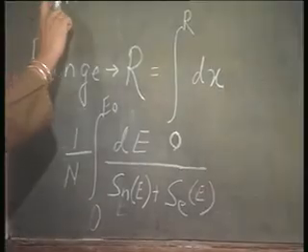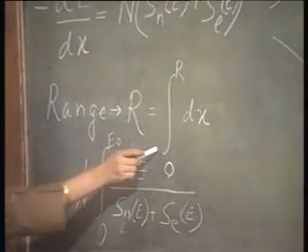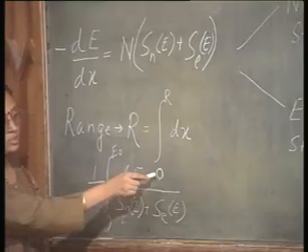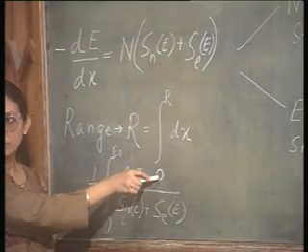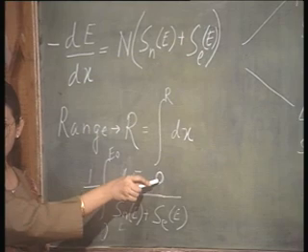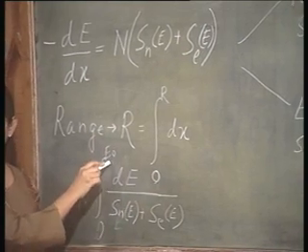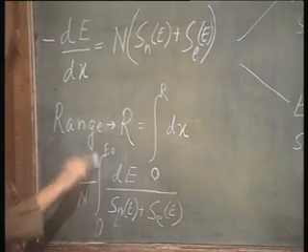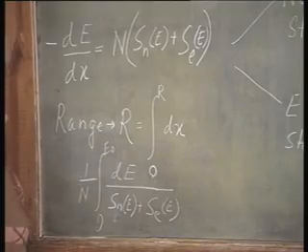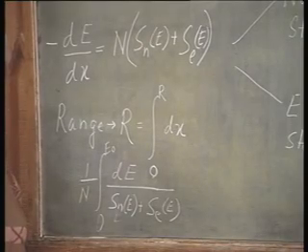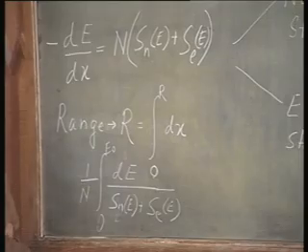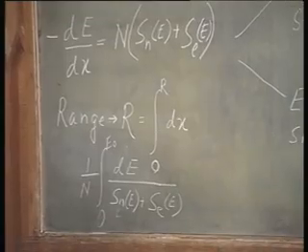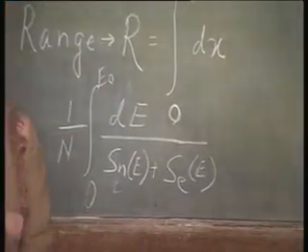See, all I have done is I have taken this dx, integrated it in the range 0 to R. R is the point where the energy is falling to 0 and 0 is the point where the ion beam is just entering the semiconductor, that is where its energy is E0, that is the initial value of the energy. The minus sign I have taken into account by changing the limit, it should have been from E0 to 0, I have changed it from 0 to E0. Okay? So, this is the equation for the range of ions.